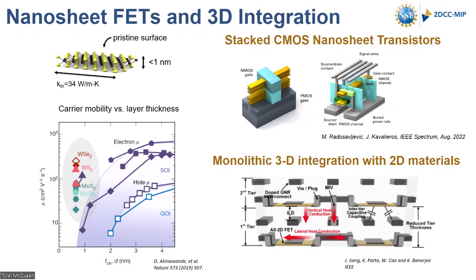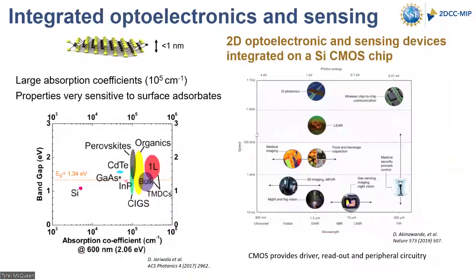So now, rather than having your P-type and N-type devices, which is your CMOS, next to one another, you could stack them vertically, right? Or you could start to monolithically integrate tiers of transistors in the third dimension. So that's really where the semiconductor field is going. They're starting to go to making vertically stacked devices, really trying to compact things, again, to put more transistors into a given area, right? So this is where there's excitement in terms of potential applications for 2D semiconductors.